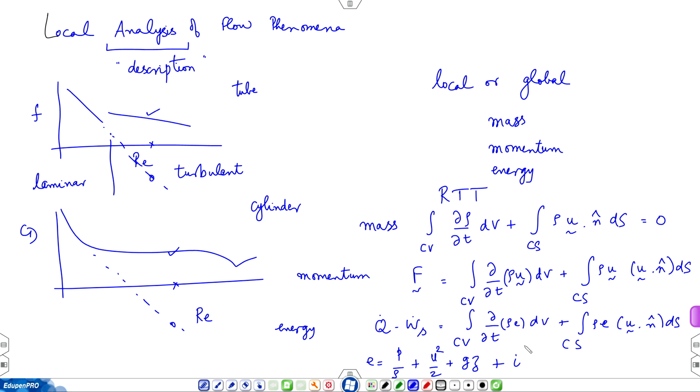So in the previous calculations, internal energy was taken to be constant and temperature was given. In a problem where heat exchange, for example, a tube is heated. Let us say you have a tube in a solar collector and it is heated by solar energy. So temperature warms up. So this is the equation to be used, where the heating rate Q dot is given to you and you find through this equation the change in temperature.